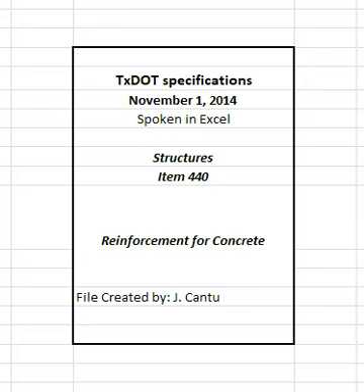Use Class 1 supports, approved plastic bar supports, precast mortar, or concrete blocks when supports are in contact with removable or stay-in-place forms. Use Class 3 supports in slab overlays on concrete panels or on existing concrete slabs. Bar supports in contact with soil or subgrade must be approved. Use Class 1A supports with epoxy-coated reinforcing steel. Provide epoxy or plastic-coated tie wires and clips for use with epoxy-coated reinforcing steel.